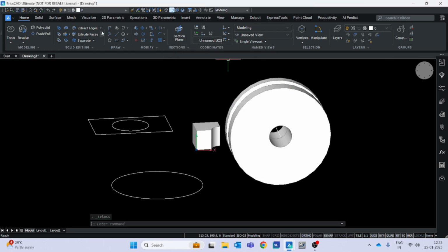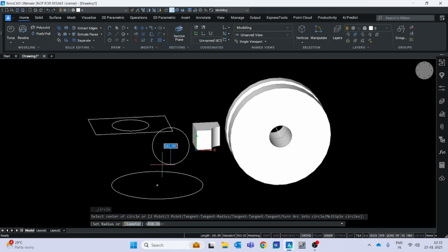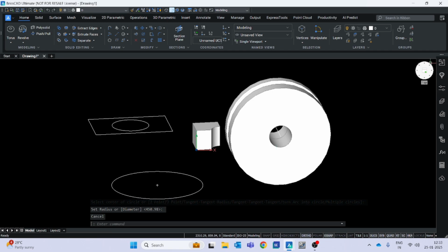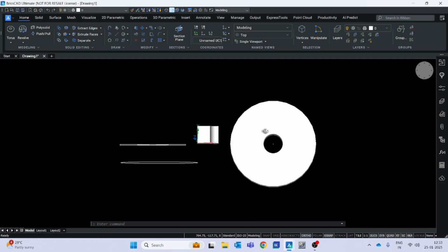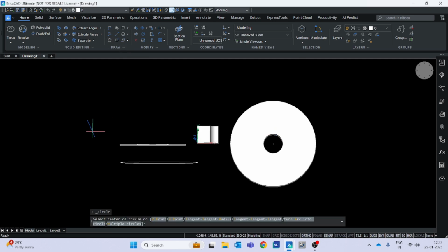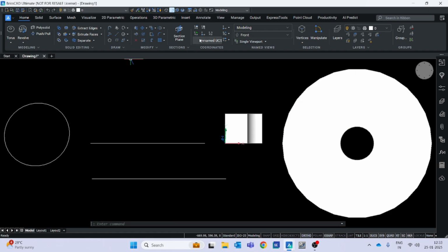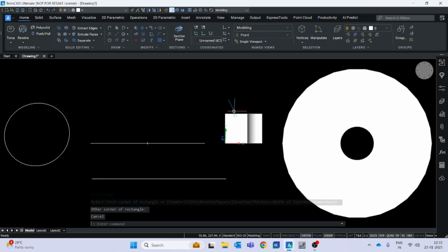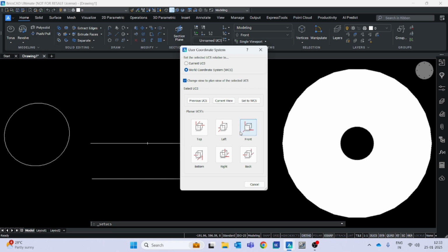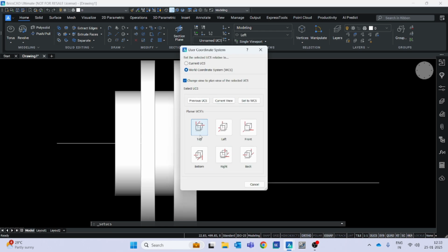So now you can draw in this particular plane, and it appears under your plane. You can make use of the UCS settings to bring your 2D plane setups into a desired plane to draw the setup.